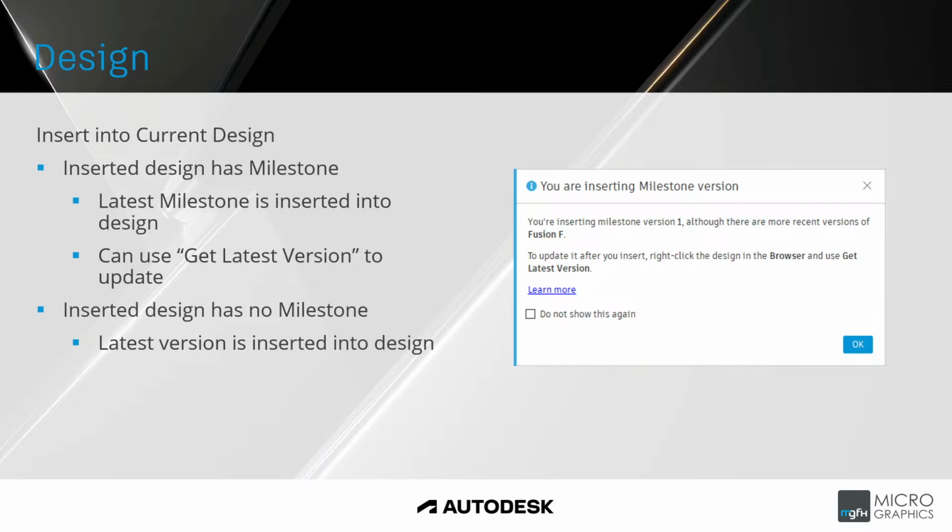If there are any newer versions going through iterations and being changed, you don't get a notification about those updates. As you bring this milestone in, you will get the warning you see on the right hand side, more of an information dialog box, saying you're inserting a milestone version. In this instance, for the part that I inserted, it says I'm inserting milestone version 1, although there are more recent versions of Fusion.